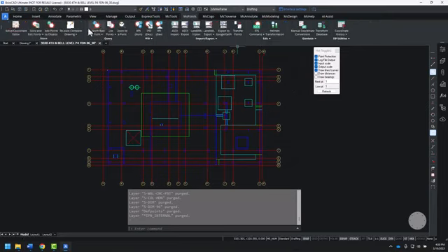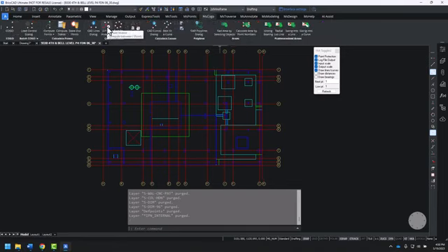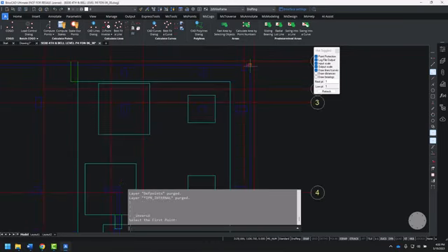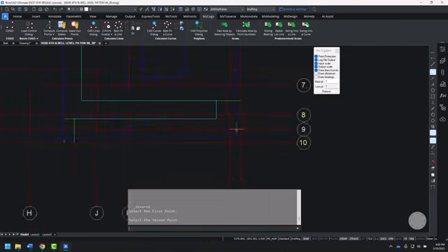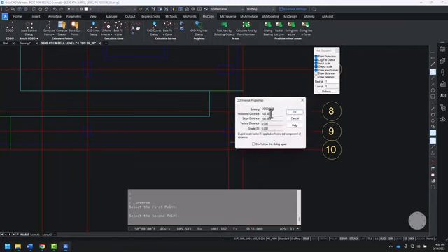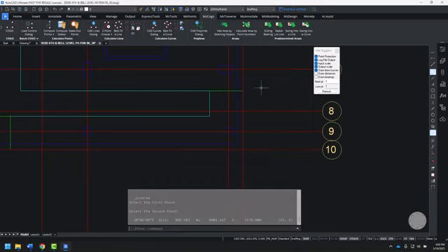Now I want to check the units. On the MS COGO ribbon, in the Calculate Line section, you can choose a 2-point inverse. By picking points on the drawing, I can snap from one end of the foundation line to the other. We see it's a distance of 105 feet. This drawing is in the correct units.